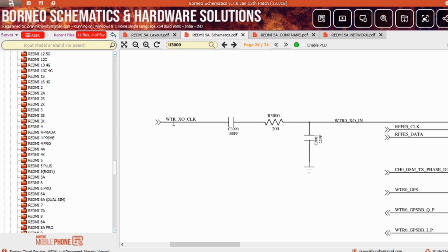In this line you will see a capacitor in series, and also a resistor, right? The capacitor is in series because a capacitor passes frequency well, and this is a clock signal. So the capacitor passes the clock signal well. That's why the capacitor is also used for noise clearing.